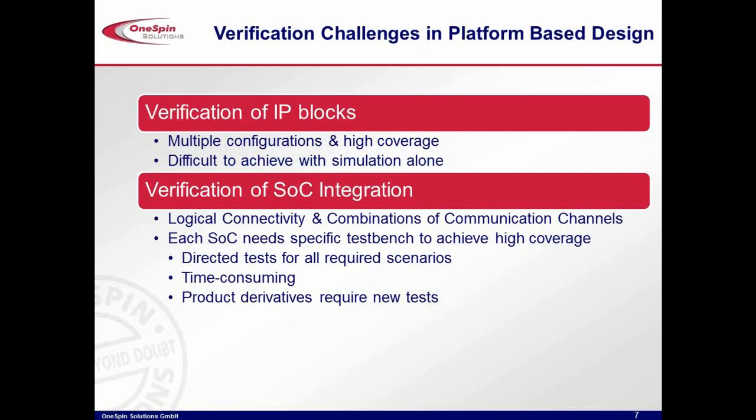So really, we have two different challenges here. Obviously, you want to have your IPs properly verified. You want to be able to reuse your verification. You have a new instance of your IP, you are using different parameters, and you want to have high-quality verification. Then on the SoC level, you have to check logical connectivity. You want to check communication channels, all the various paths between master and slaves. We have seen quite a lot of these.